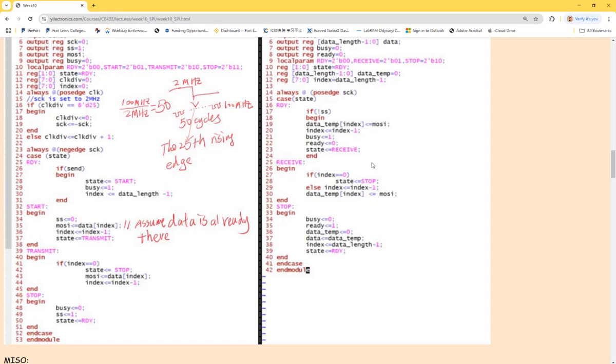Okay, another very popular application for SPI is SD cards. I have a lot of SD card adapters in my lab. You can find an SD card adapter, plug in the SD card, it's usually SPI, right? Just write all the protocol, and eventually communicate with the SD card to write and read data in and out. It's another really fun project. So it could be a sensor, from light, from a sound, anything, eventually being digitized and stored in the SD card. Okay.